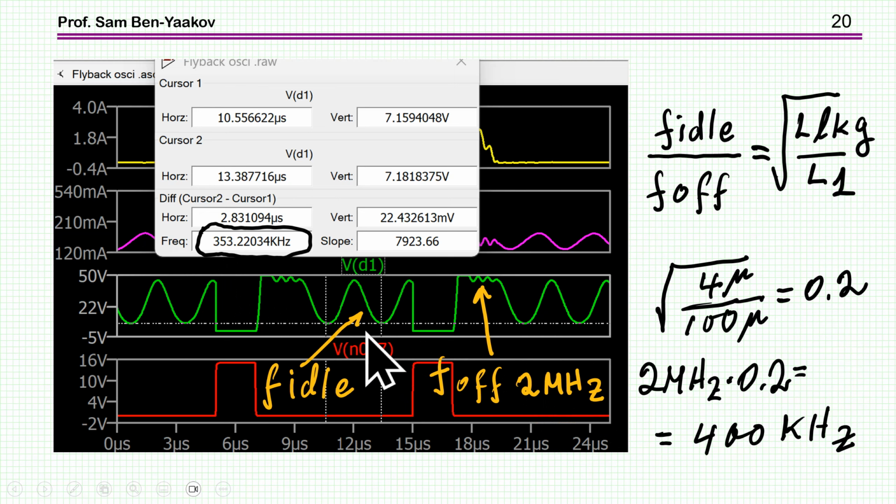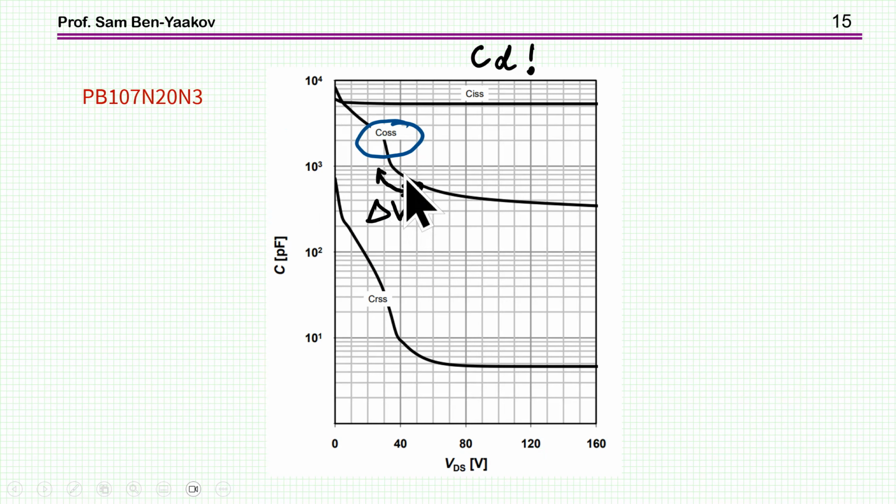Now, again, we are not taking into account that this is a non-linear capacitor, and as the amplitude is increasing, the capacitance is actually increasing, the total large signal capacitance. So therefore, you would expect the frequency actually to be lower, which is consistent with what we see.